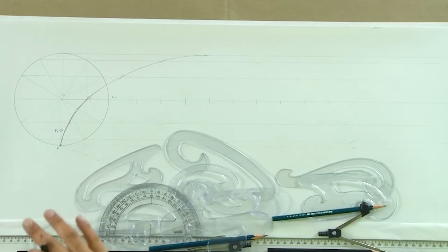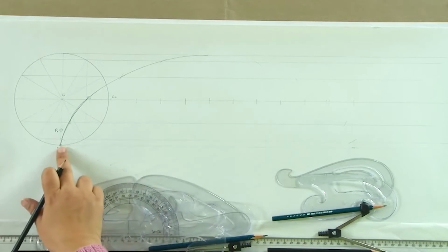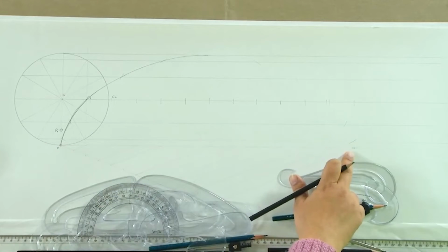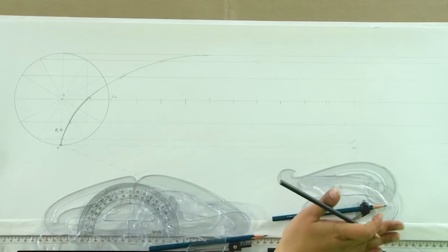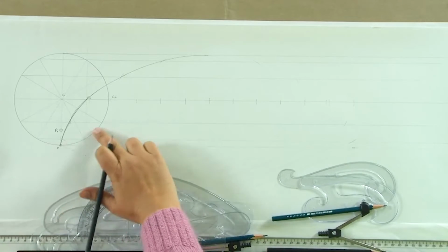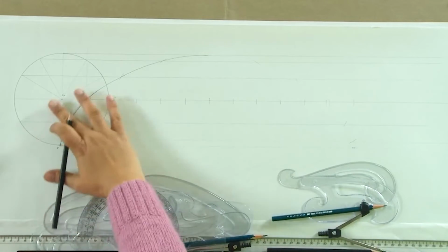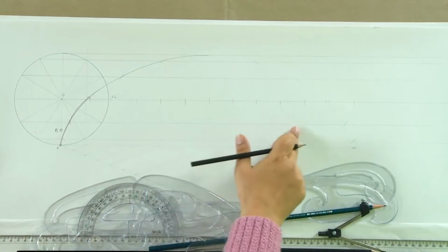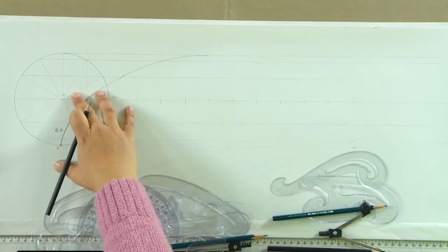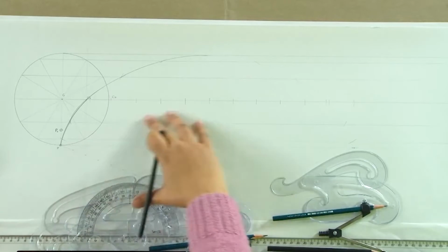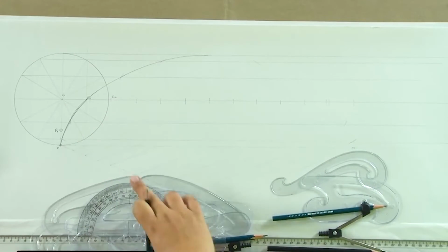exactly the same process. If we are to draw epicycloid, in that case the only change is that this length of the circumference which we have drawn as a straight line would actually be taken on a circle. So, whatever circular path the circle is going to trace, we would take the curve, the arc of that circle where this smaller circle would be moving, and that circumference would be divided into equal number of parts, and exactly in the same manner, instead of these parallel straight lines, we would be drawing concentric arcs at the same distance from the center.